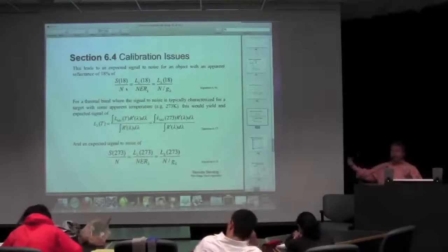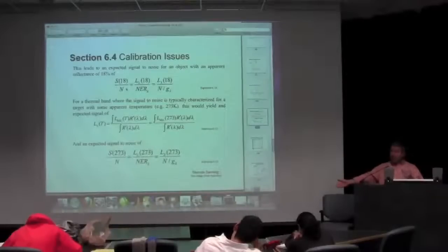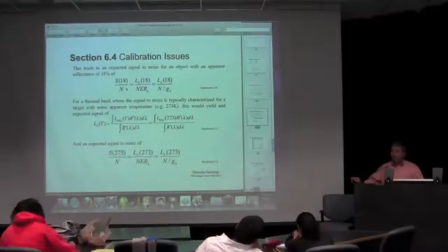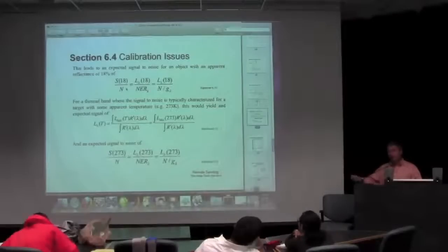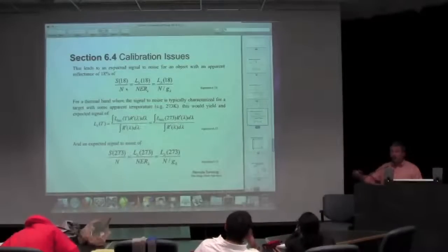And that's a very powerful thing to have, because if you have a sensor now and you want to go do a measurement of water in the near-infrared wavelength bands where there's not a lot of photons there, you want to know what that signal-to-noise ratio is to know whether or not that sensor is going to be sensitive enough to see the small change in reflectance of the water surface that might result because of, you know, a phytoplankton level or something that you're trying to measure.